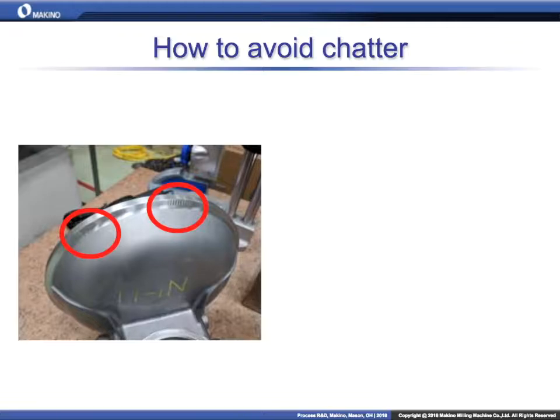So the first thing I did was I looked at both the workpiece and the tool. The tool was a 2 or 2.5 inch diameter form tool that stuck out maybe an inch. So fairly stiff tool. And I looked at the part, and it's sticking out. But it goes ding, exactly. So I recognized right away that it's probably the tool that is the most flexible element. Or most stiff. The tool is most stiff. I'm sorry, the part is the most flexible.